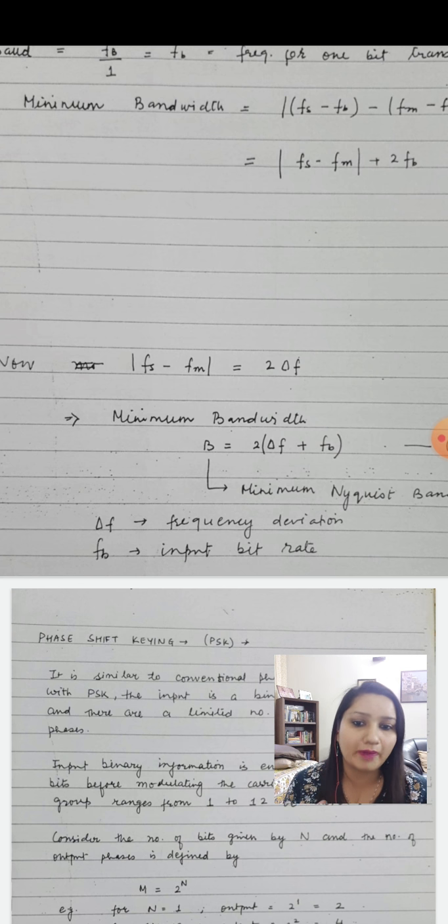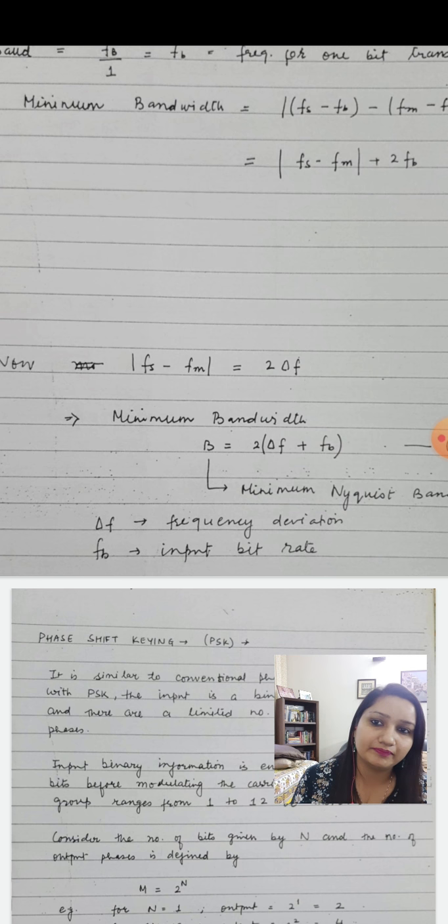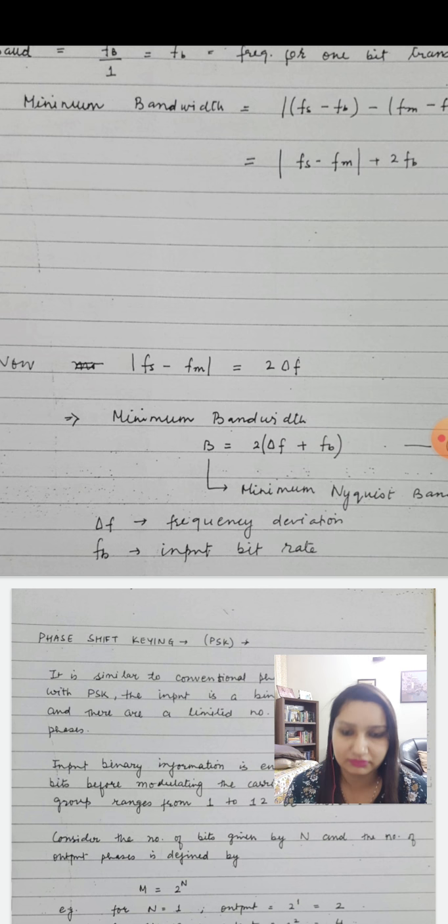So there are four parts to every modulation. First is the definition, second is the characteristic equation, third is the cases according to which you derive what is going to change in the output, and number 4 is your bandwidth or baud and the relation, that is the minimum bandwidth, maximum bandwidth or the deviation.